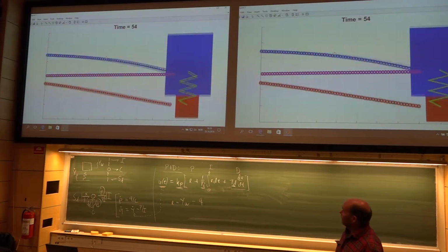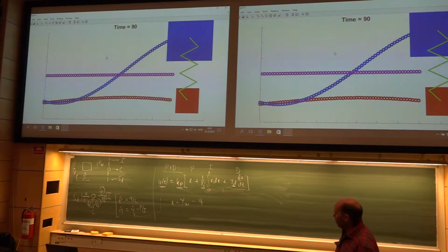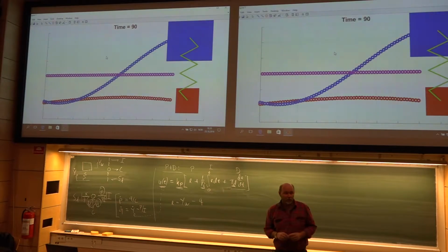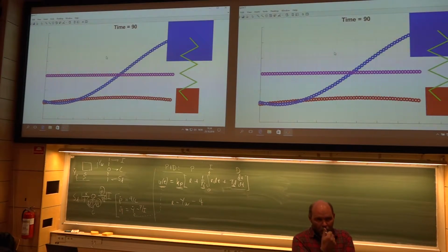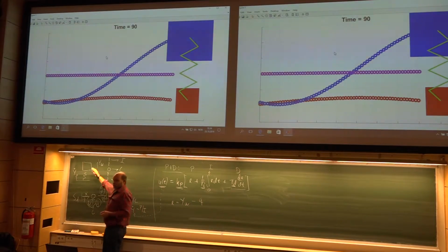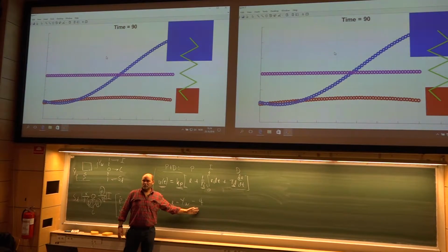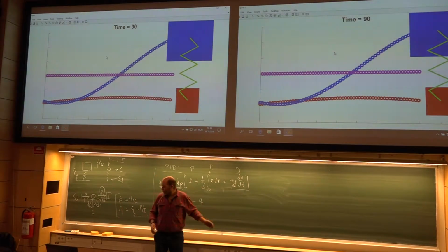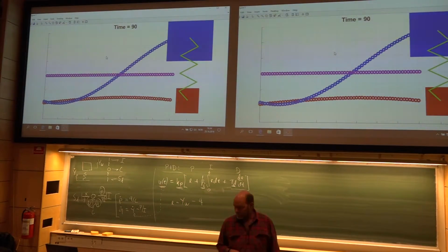So here I was getting depressed. So what's wrong? What's the error here? Where have I gone wrong? Any suggestions? Not so easy to see. Remember the problem here, the task. Adjust to a specified position. The error is defined as difference in position. Then you must not adjust a velocity. You must adjust the position. That was my mistake. I'll show you.